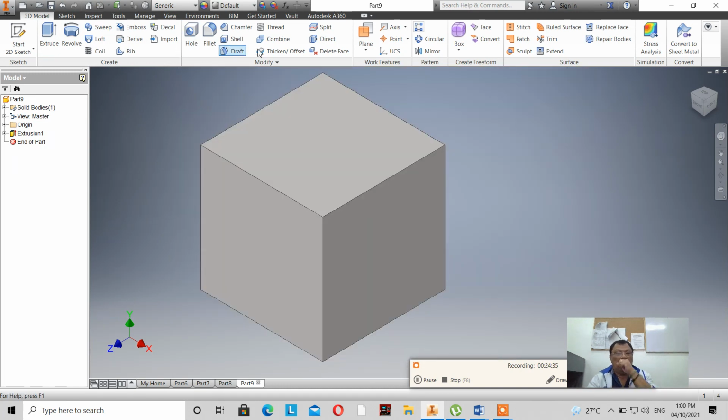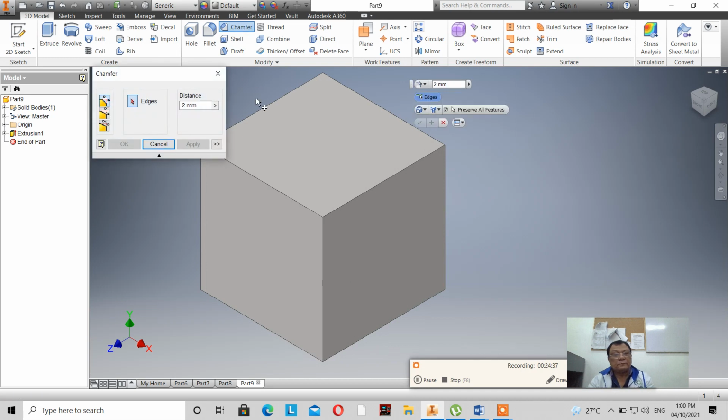Now, when I click on the chamfer tool, I will have this. I can click to minimize it or to maximize it. Now these functions are also here. So distance is equivalent to this, distance and angle is equivalent to this, and two distances is equivalent to that.